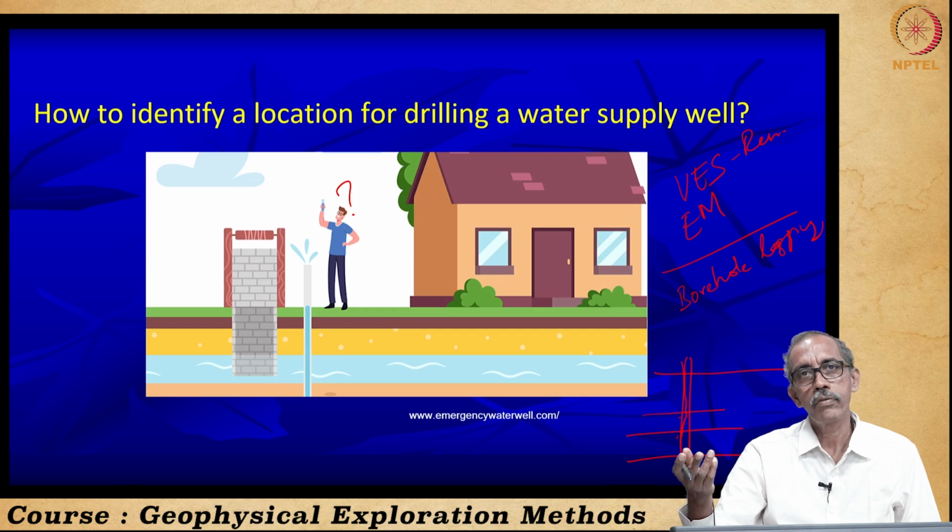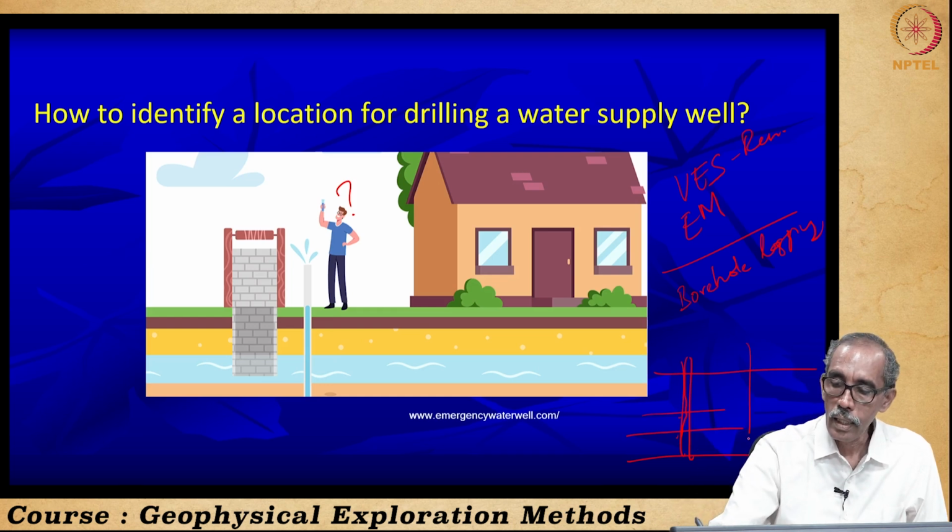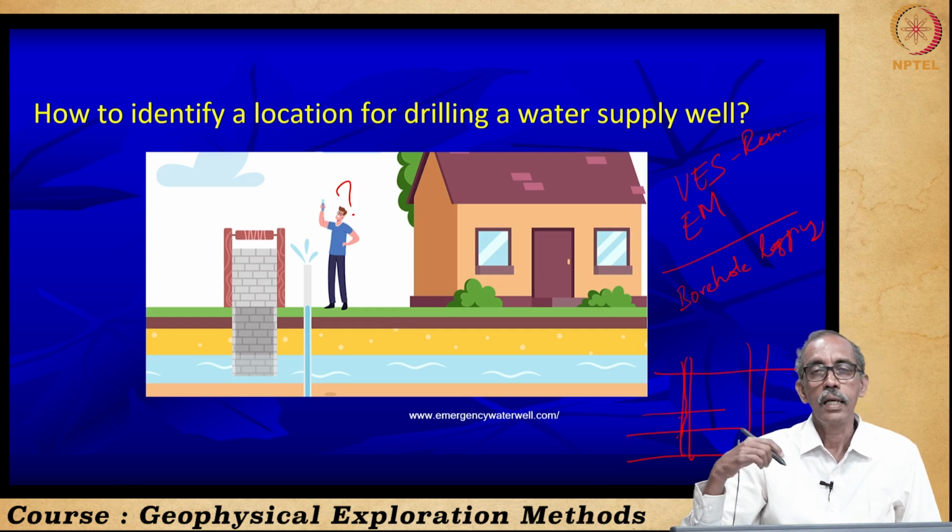We had seen it toward the end of this course during the 12th week, just before this, different borehole logging methods using which we can determine the porosity of the formation, and approximately we can determine the hydraulic conductivity. So, borehole logging methods can also be used to identify a potential site for drilling a borehole, and also within the borehole, the potential location for placing the well screen can be answered using borehole logging methods.